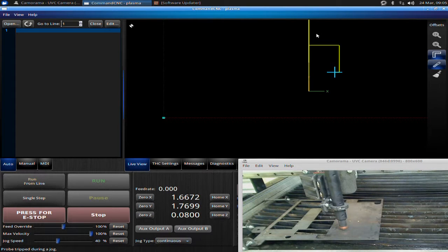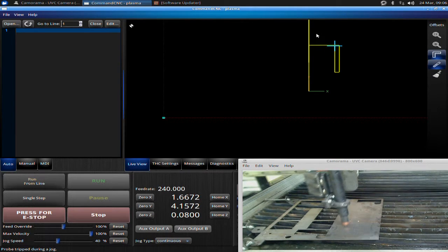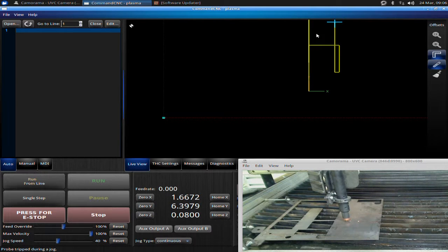Let's talk a little bit about how you recover. We've discussed different ways that you can lose position. So now I'm going to cause the machine to actually lose position. I've purposely set a wrench on my rails in such a way that it will jam up the machine in its motion. And you might be able to hear that. You can say, oh, my machine just jammed up, and so the gantry is completely out of square. My machine thinks it's in a completely different location than it is right now, because the motor stalled, and so everything's completely out of whack.